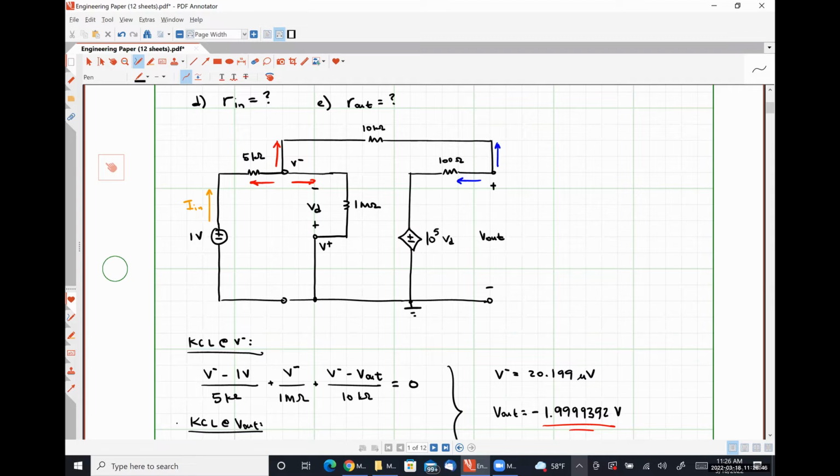If we were applying our input signal to the non-inverting input terminal, we would see a scaled version of this capital Rn value that's scaled by the amount of feedback, okay? So effectively, looking in this way, we see this resistor in parallel with an astronomically huge resistance.